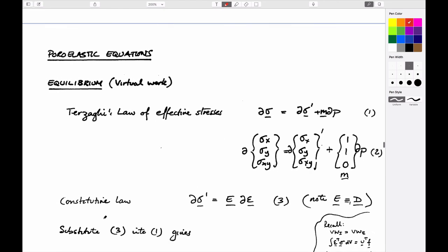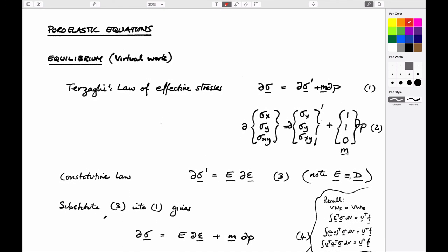So our approach is this. We want to be able to solve the system equation, so we divide it into two parts. We have the solid mechanics part, which we'll deal with first, and the fluid mechanics part, which we'll deal with afterwards. The solid mechanics part, the derivation would be exactly the same as we've done for solid mechanics, with the modification that when we talk about total stresses in our system, we write them in terms of effective stresses. We can write them as total stresses being equal to effective stresses plus fluid pressures.